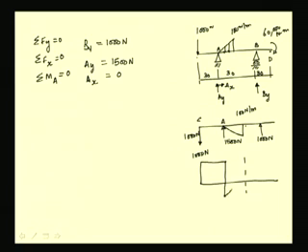We know that it has to be a quadratic curve and the total area under this curve is 1500 Newton, and thus it rises to the point with positive 1000 Newton shear force value. Between this portion and B we do not have any change, and at B we have this 1000 Newton positive force, and so the shear force curve comes down. These are the various points.